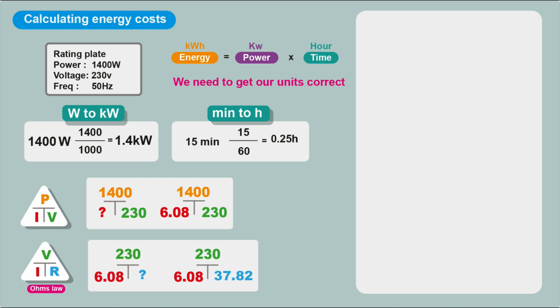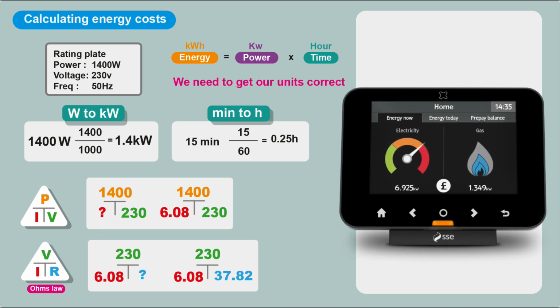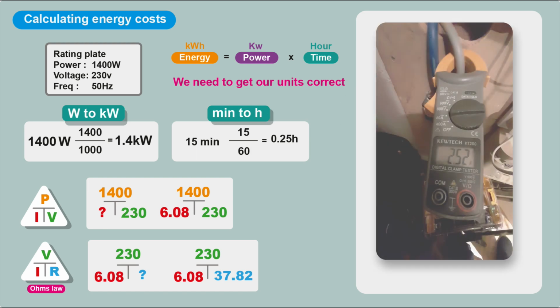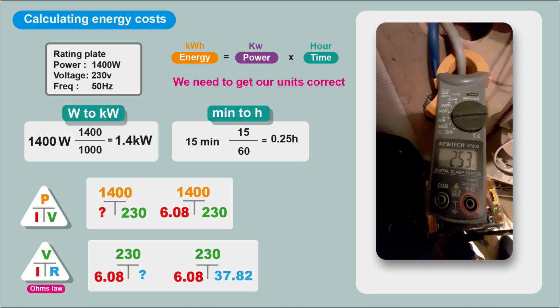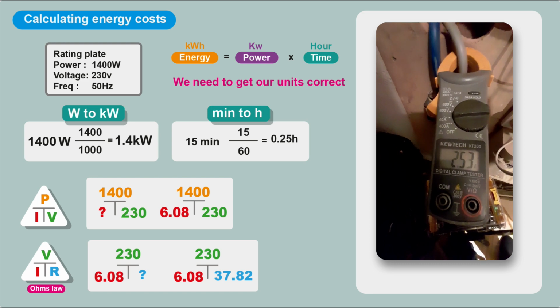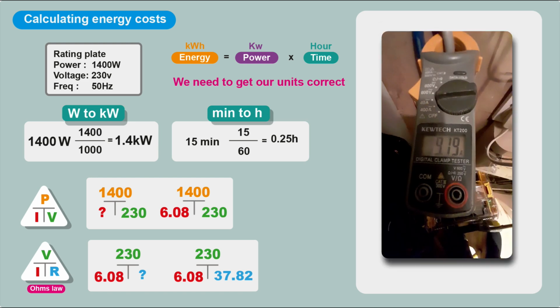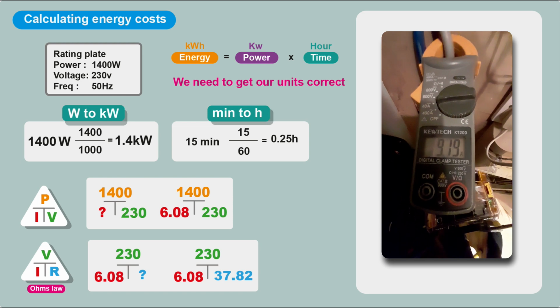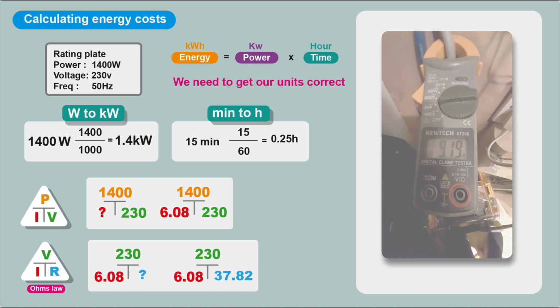You can, of course, get energy meters that'll give you a constant update of what power is being used. Or clamp meters are quite useful. You can take a couple of readings off the meter tails, to get your background usage so you know what's being used, and then you can switch something on like an oven and you can measure the current that the oven's using by the increase on the clamp meter.